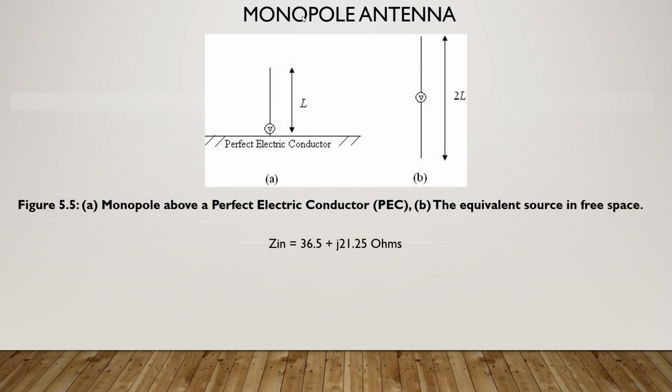That is, the directivity of a monopole antenna is twice the directivity of a dipole antenna of twice the length. The reason is simply that no radiation occurs below the ground plane, hence the antenna is effectively twice as directive. Monopole antennas are half the size of their dipole counterparts and hence are attractive when a smaller antenna is needed.